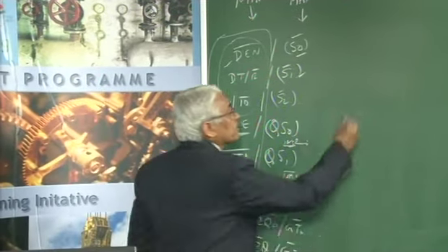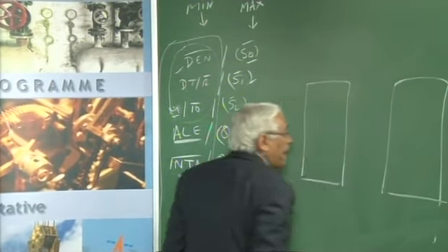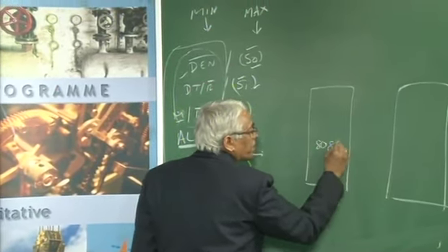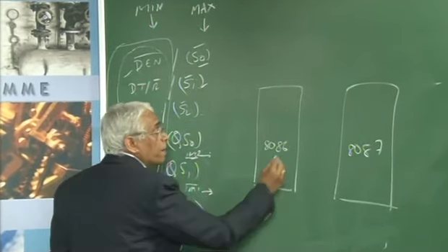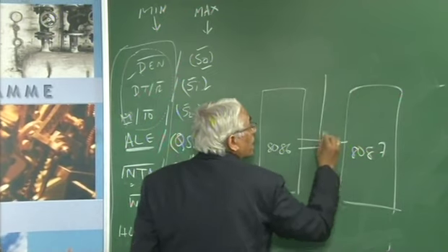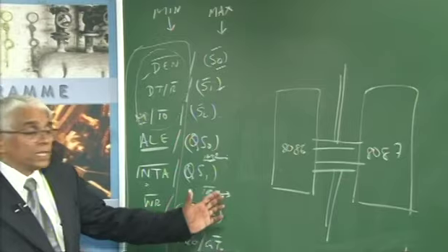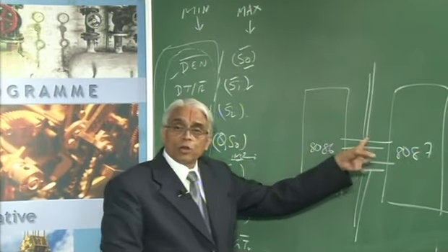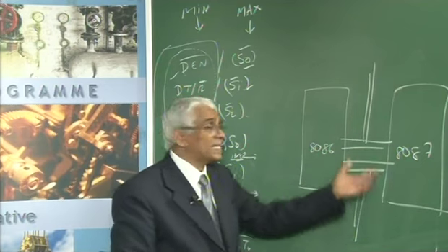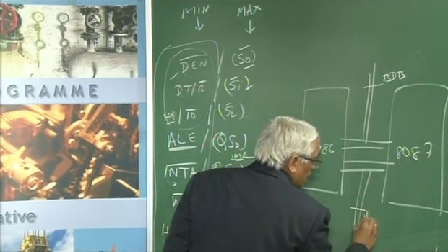But the coprocessor is connected in parallel to the microprocessor. So when we talk about the 8087 coprocessor, these are connected together, having a common data bus and address bus. I am not showing the demultiplexing, latches and other things. It's assumed that it's all there. I'm just showing an address bus and a bidirectional data bus.